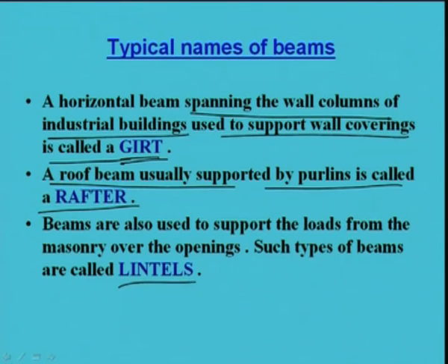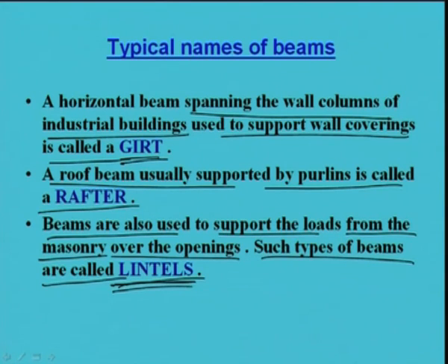Another is lintel, which we will see used in RCC buildings. Beams are also used to support the loads from the masonry over openings. Such beams are called lintels. That means, when windows or doors are there, we provide a beam which is generally called a lintel.